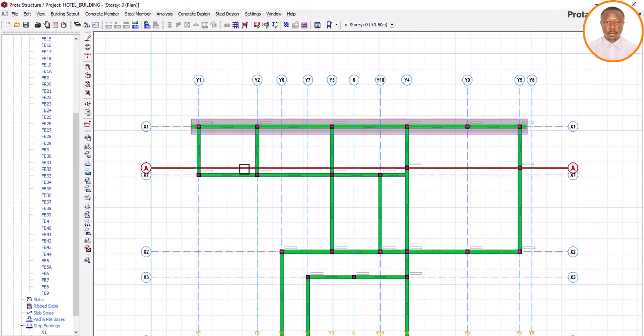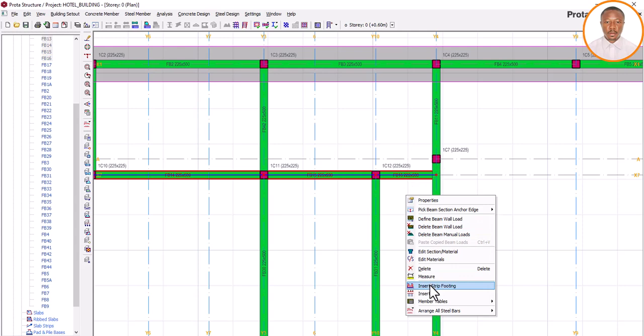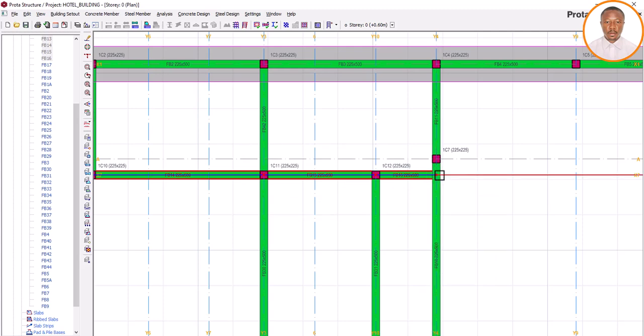Do you see it? So the next thing, we also click on this. Let me start with horizontal first. Click on this, press shift down, and click the rest. Now, I want to show you something at this point. If you click on this, because there's no support here, it will not work. Let me click on this, and then remove my hand and right click, and come to this place. So you can see it. Missing column. Do you see now? So I close it. Which means this particular one, there's no column.